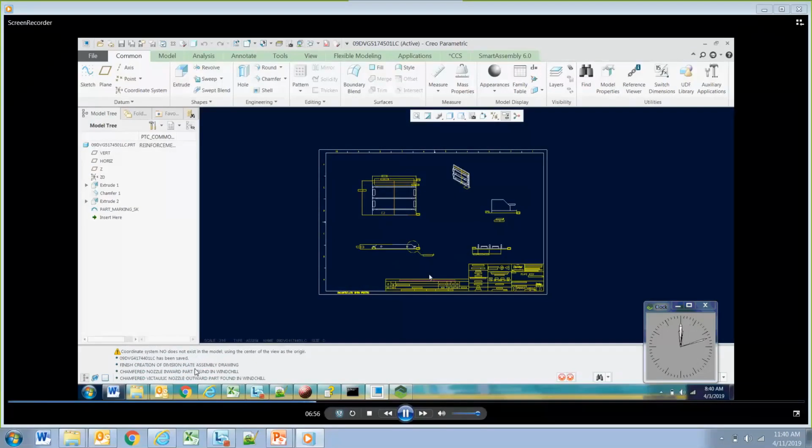As you're watching the drawings get created, just as we saw in both the copper tube and the tube sheet tool, it's placing all of the dimensions, the engineering notes come in, and you get a fully filled out rev block and title block. The only thing that you're doing is cleaning up a few things here and there for legibility, and modifying layer status as you go if need be.